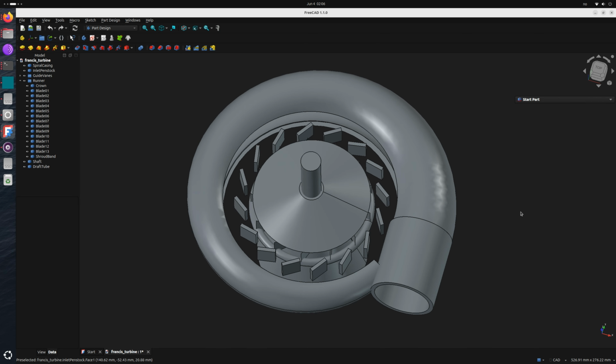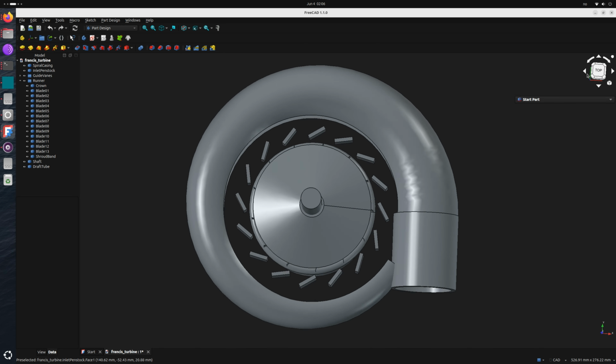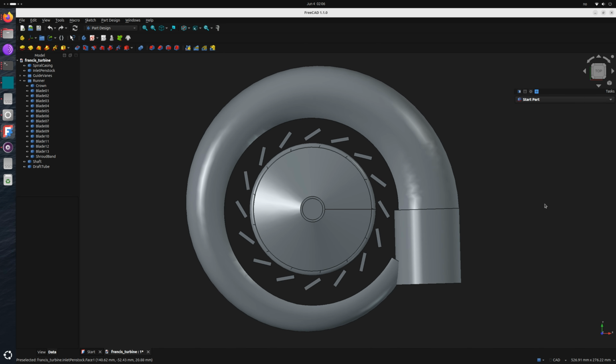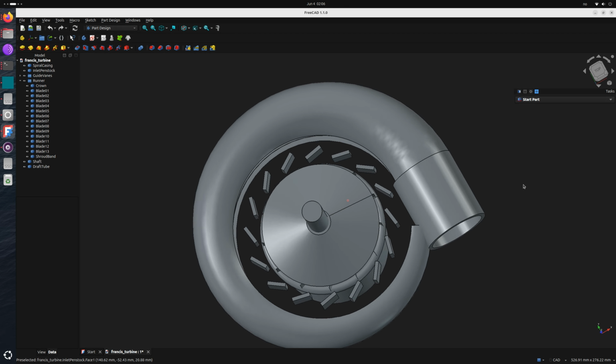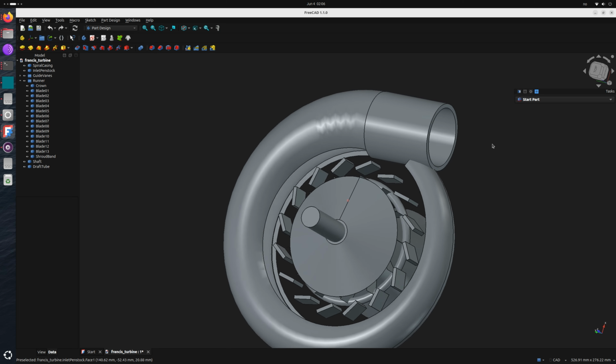Kvilldal, the country's largest, is Francis, around 1240 megawatts under roughly 500 meters of head, with Tonstad in the same heavyweight class. Solid head and solid flow. Francis is almost always the winner.